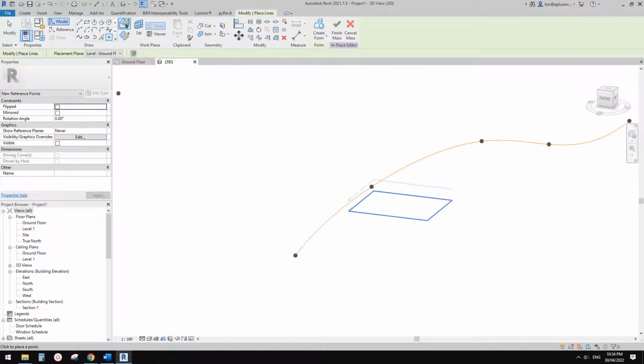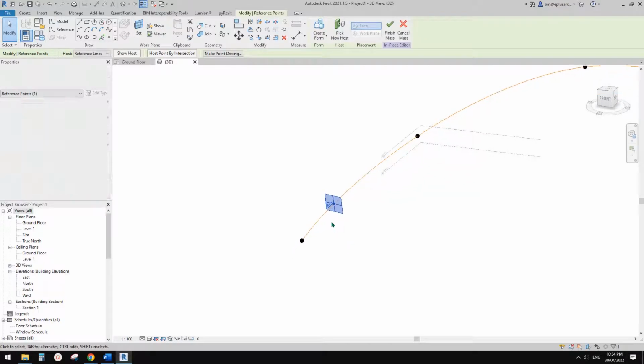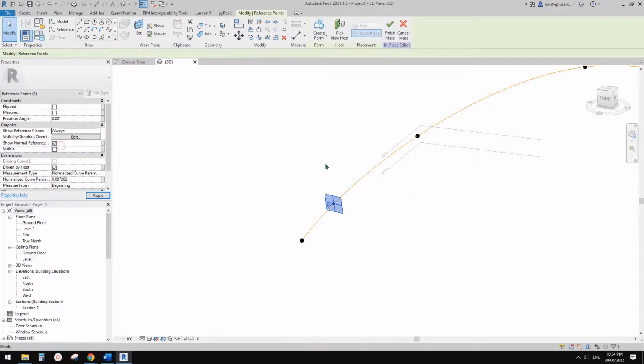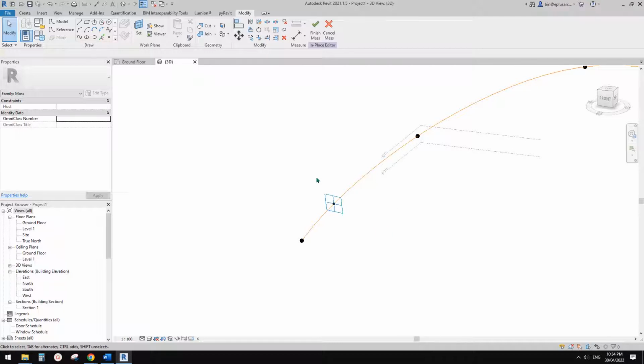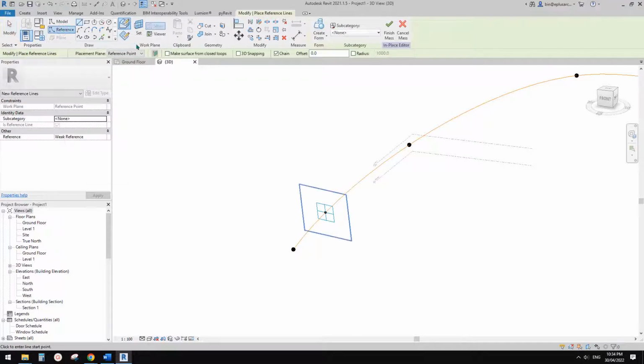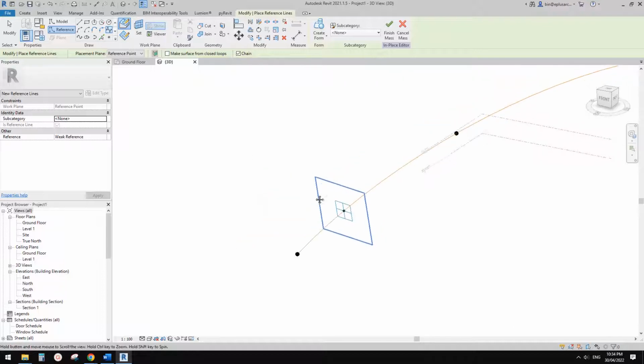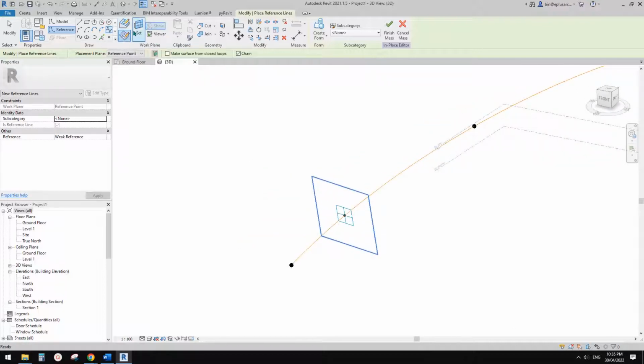Okay, and then we just need to place some points, draw on face. So this point can be used to place profiles. For example, I'll place 1 point here. And then if I change this to always, you will see this is a work plane we can place profiles on. So let's just do it. I'll try spline. Because the profile will be placed on this work plane only, it will be a flat spline. So draw on work plane, set work plane, pick this work plane, and then we can start to create a shape.